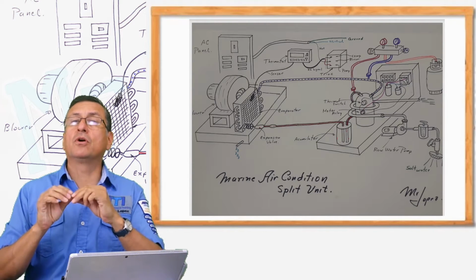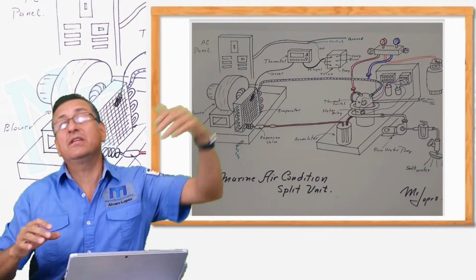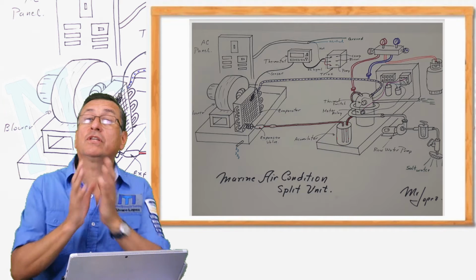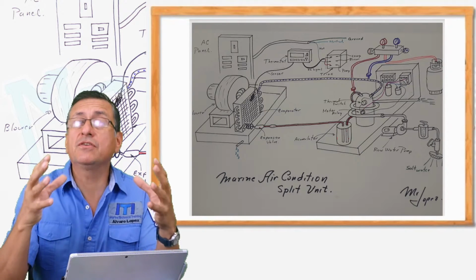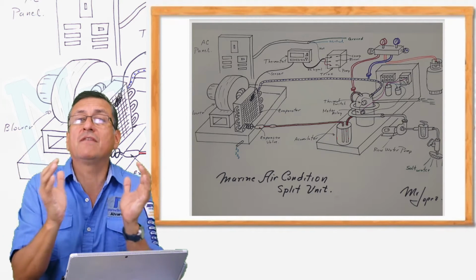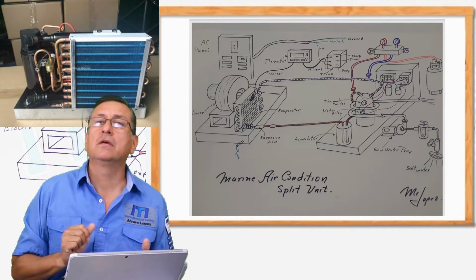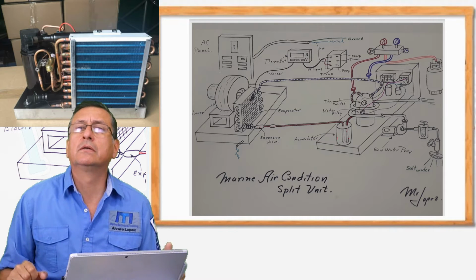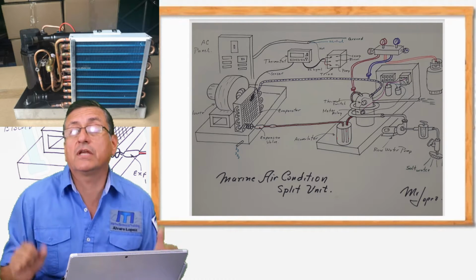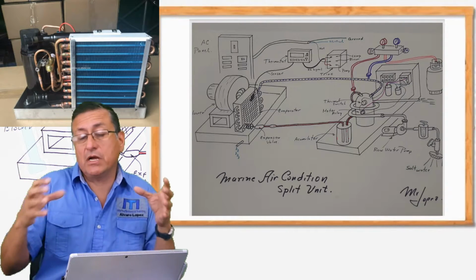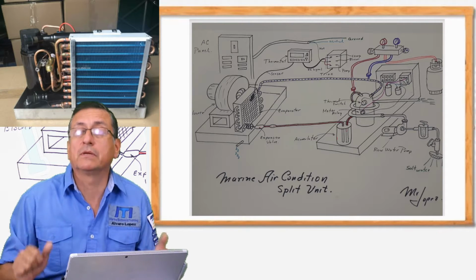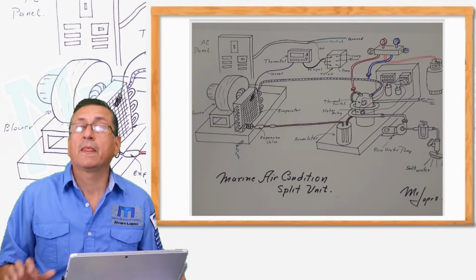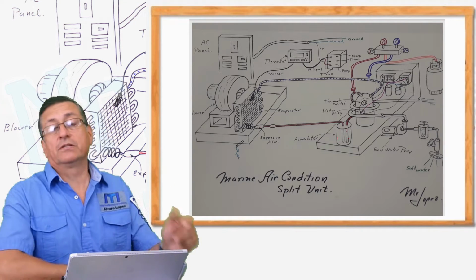You need to transport refrigerant for a long distance between the condenser and the evaporator. For that reason, some technicians, some engineers prefer the self-contained unit like this, because that unit has the compressor and the evaporator together. Those are self-contained units. The compressor and the evaporator are pretty close in the same compartment. This is a good advantage. That's the inconvenience of the split units.